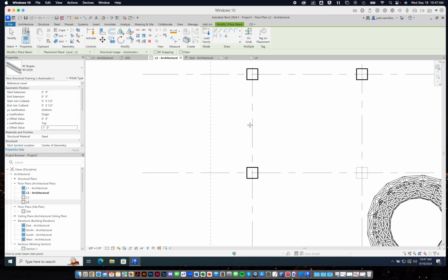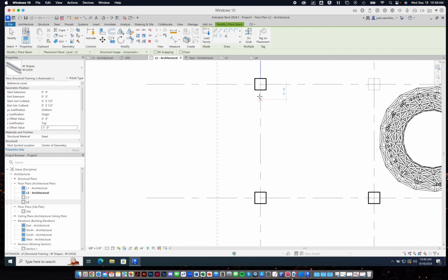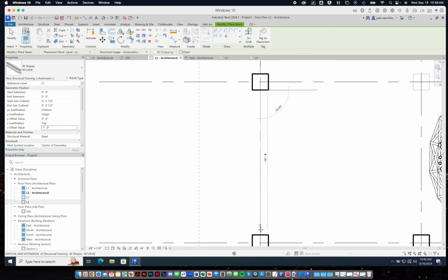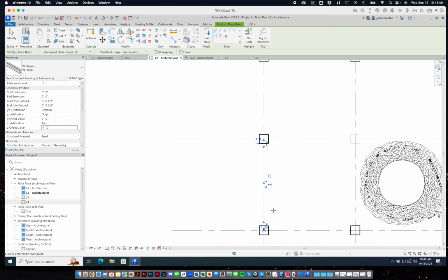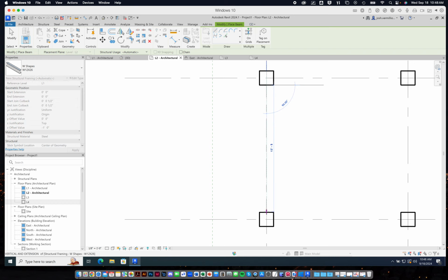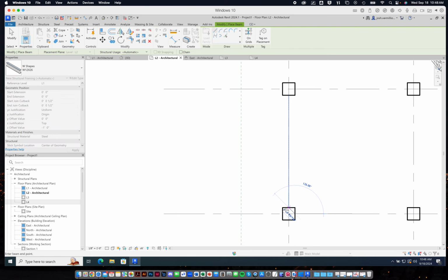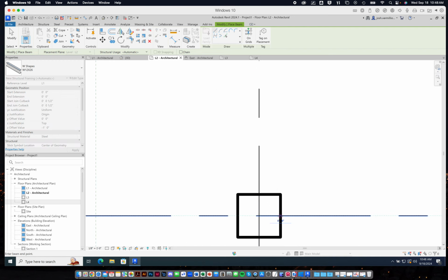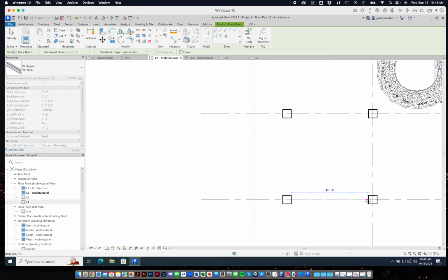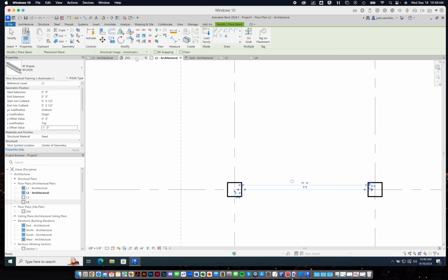I've already done this one, so bear with me here. I'm going to try to make them flush so they look like they're actually framing into the side of these columns, as if maybe the columns are really beefy hollow steel tubes. Maybe I'll come over here and do it over here. These are 18 by 18 inch columns, so when I find a point over here, it's usually 9 inches away from the center line. Just simple arithmetic. 13.5 feet long. Let's look at the 3D model.